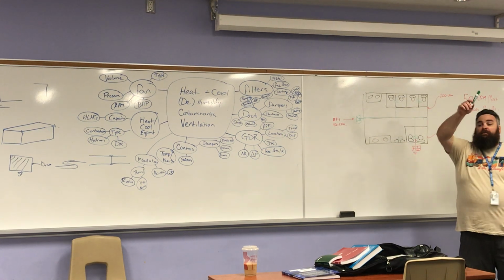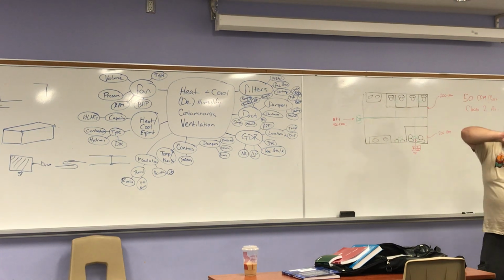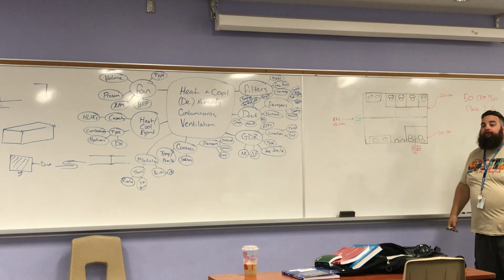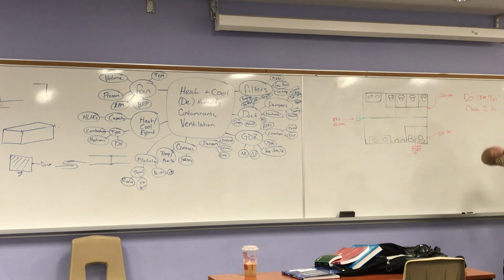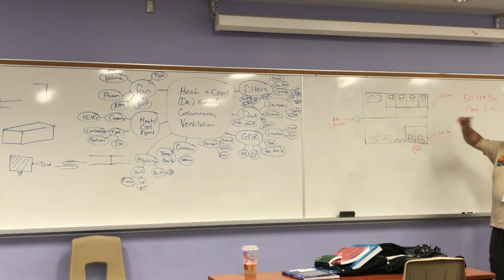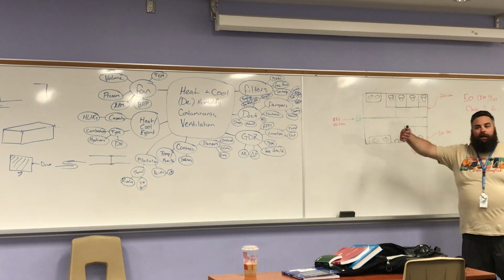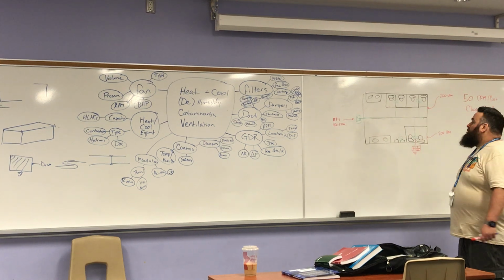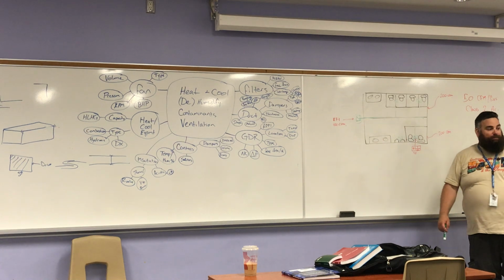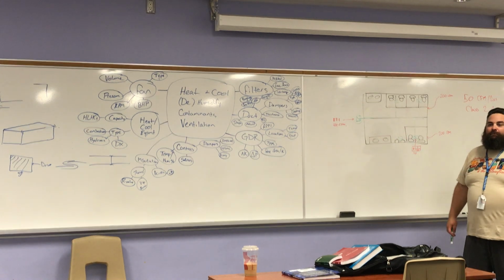These are light troughers. These go in a ceiling grid, and there's probably about 4 to 6 inches above it into the ceiling area. If I don't have a lot of clearance there, that might be an issue. What else? Servicing, like water, gas. Yeah, any other pipes? If there's a bathroom above us and we have drainage pipes, they take priority because they're gravity. What else? So a lot that goes into it. Sprinklers. The sprinkler pipe.